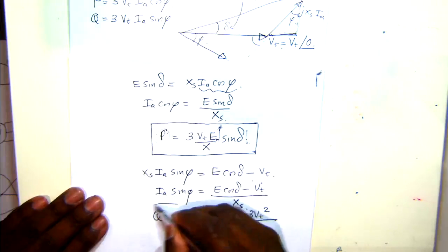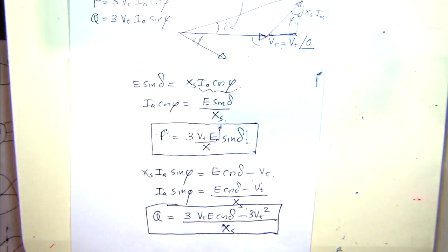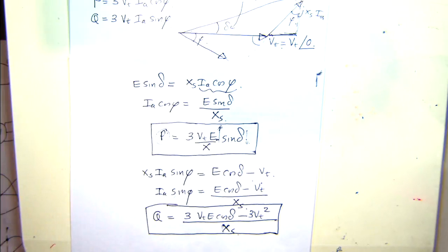So these two equations are the main equations that count real power and reactive power. So as I mentioned earlier, let's say it's delivering the same amount of real power. You change E and then delta will change to maintain that same real power. But then if you change E and delta, this whole thing will change and the reactive power that you transfer to the grid will change as well. So it won't remain constant.